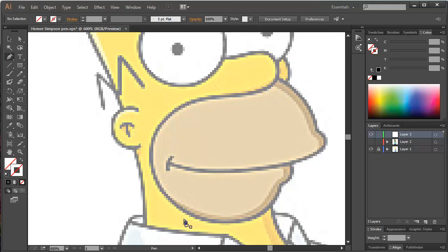And you pick a point to start. One trick to the pen tool and tracing something is make a lot of paths. So this will be one path, a separate path. This will be a separate path until it joins up here. If there's kind of a 90-degree angle somewhere, or if it comes up perpendicular to something else, then you make a new path. You don't try and continue it. So, with the pen tool, click and drag, and that pulls out your anchors. And the longer the anchors, the more curved your line's going to be.